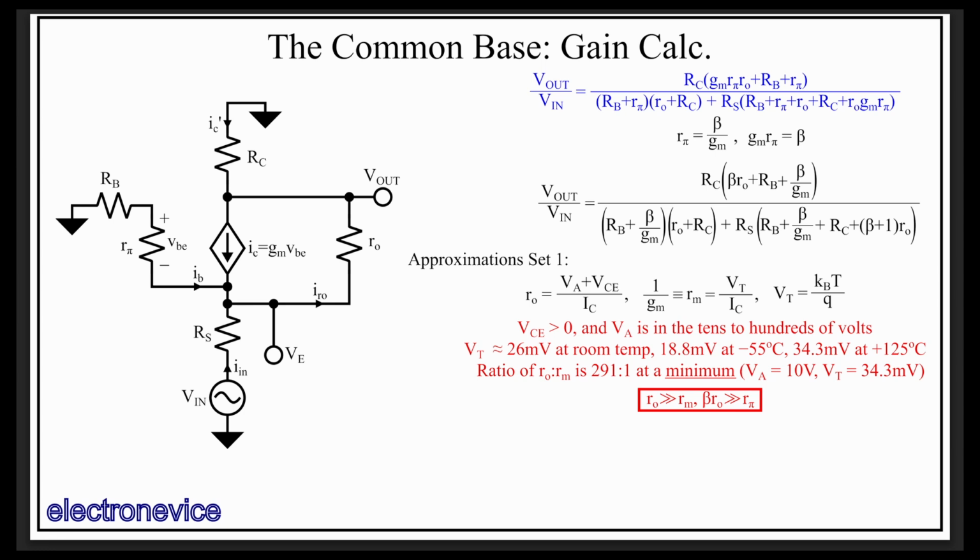As a reminder, we take much larger than and much smaller than in circuit analysis when making approximations to mean greater than 10 times the value and less than 1/10 the value, respectively. So a factor of 10 is the magic number we use. This obviously doesn't apply in all situations. However, in small signal analysis, we're already using an approximation, and precision analysis tends to be reserved for more special circumstances that use a combination of test data, high-fidelity simulation data, and negative feedback to make nonlinearities and non-idealities truly negligible.